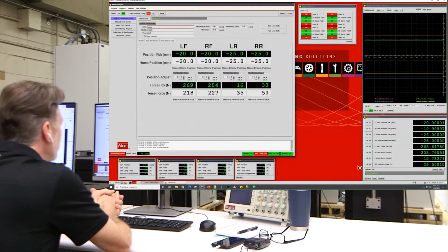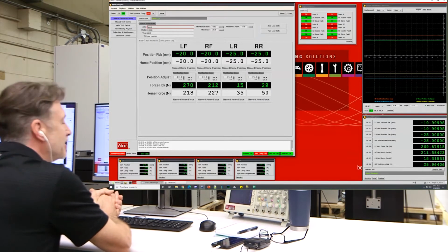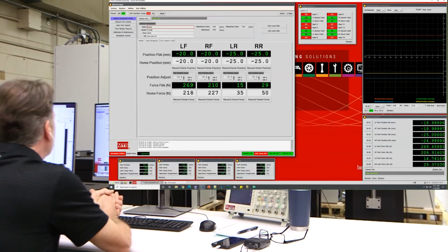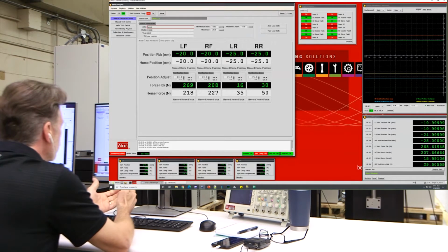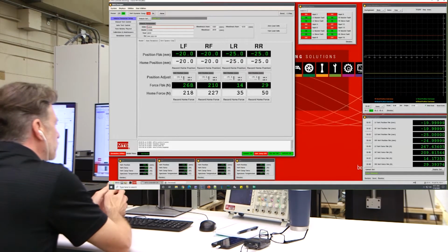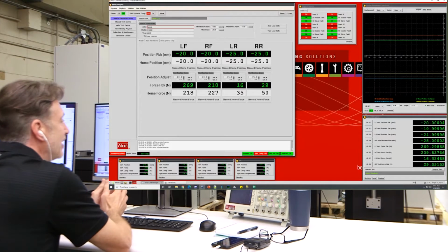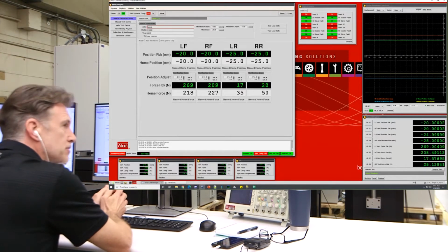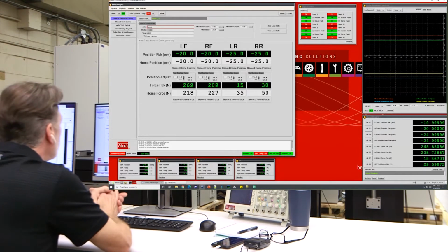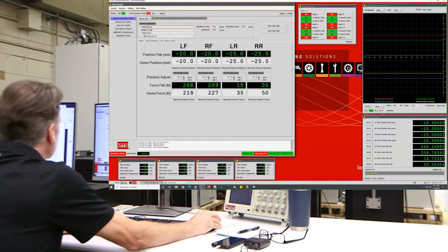What we will do is match up physically with what the kinematic tables in the damper, in the vehicle model are set up for. We want to make sure that the ride height is at the correct position within the damper. We want to confirm that the stop engagements on both the jounce and rebound are engaged at the right points, so that the system will behave as it would be out on the vehicle.